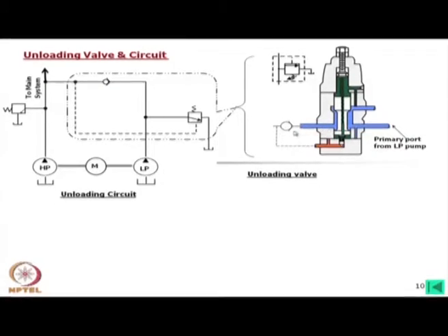Now, how is it working? You have to compare this with this figure. This is the check valve and this is the connection to operate it. This is the pilot connection. Now, this primary port from the LP pump is connected to here. So, ordinarily when this is a high pressure, this is blocked, no oil is coming to this side, but it is only remotely trying to control this valve.